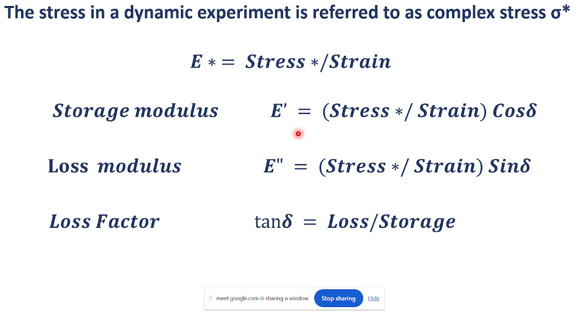And actually, crosslink density we used to measure just by checking the change in volume. If you dip a crosslinked material in a specific solvent, after a certain time it will swell. Now, with increasing crosslink density, the swelling will be lower. In that way, we used to calculate the crosslink density by checking the weight of the material. The higher the crosslink density, the lower the swelling. So I don't know whether there is any threshold for any application, and I need to know that actually. But for vibrational type applications, your crosslink density should not be very high. That is for sure.